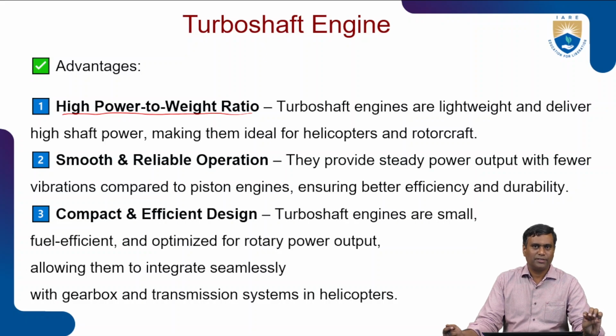It generates 100% shaft horsepower, no direct thrust from a jet engine, and they are high power to weight, but at the cost of fuel consumption, more fuel consumption when you are comparing with any other gas turbine engine as well as piston engine. But they perform well in low altitude, low speed operations.